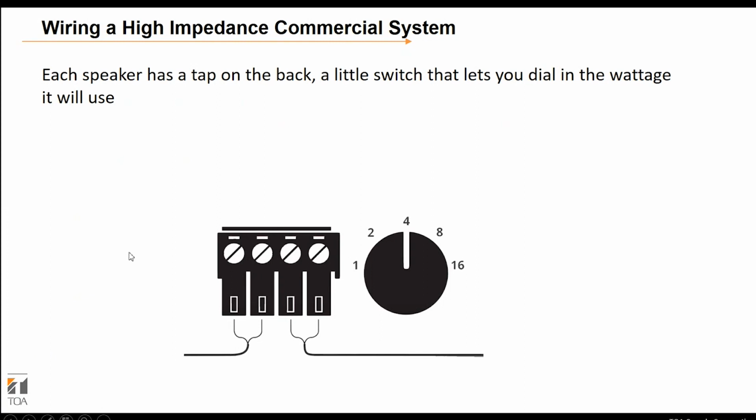In this case, and in any case with a high impedance system, about 99% of the time you'll see a wattage tap on the back. It's generally a little switch or a series of different connections that will indicate what the wattage requirement, what the wattage pull is going to be from that speaker. So you can generally set that. It depends on the speaker.